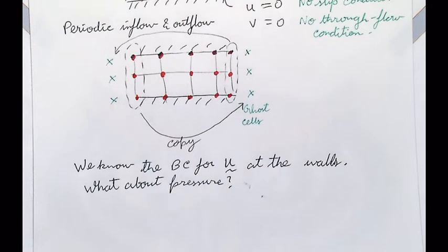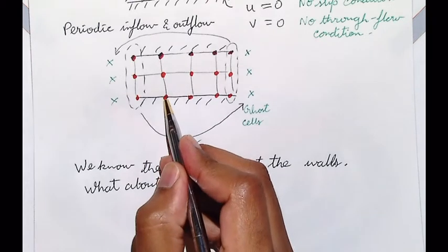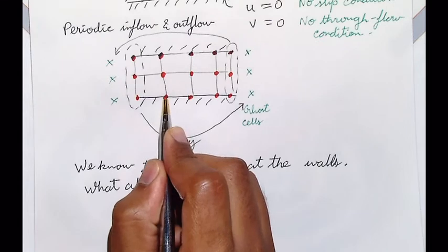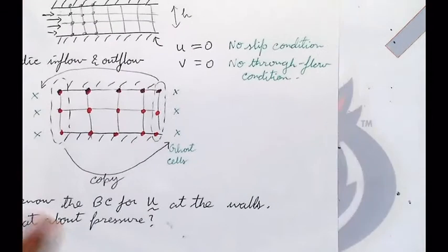Again, you might think that here we have stagnation pressure, where we can say p static plus half rho v squared. But that's not strictly true, especially because we are using this time splitting, where our pressure is a pseudo pressure.